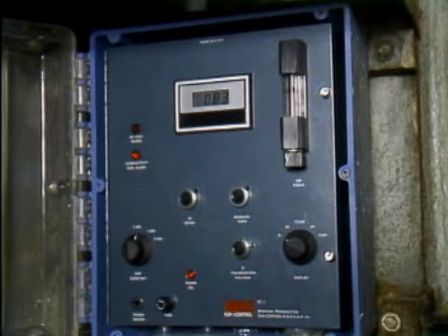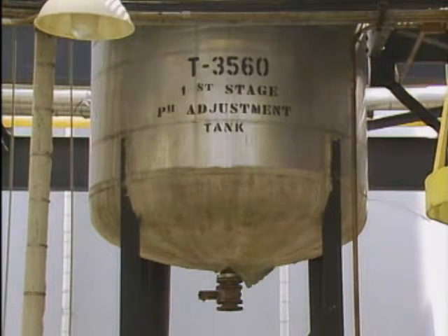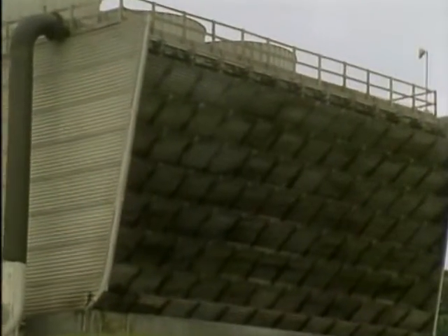pH analyzers are used in many types of industrial processes. For example, they're often used for monitoring and controlling the pH of materials involved in chemical production processes. They're also commonly used to protect process equipment. For example, pH analyzers help prevent the water in this cooling tower from becoming too acidic or too alkaline and corroding equipment such as pumps and piping.